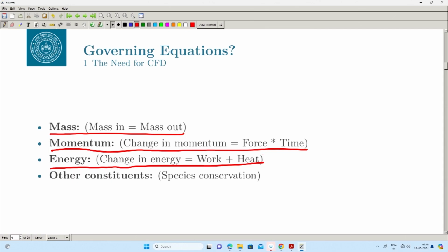It is important in incompressible flow also, but it becomes a trivial equation in incompressible flow, because you do not have any thermal energy being added that is affecting the dynamics of the system. So, you can just solve the kinetic energy conservation, which can be derived from the momentum equation directly, right. So, we do not solve the energy conservation in incompressible flow normally.